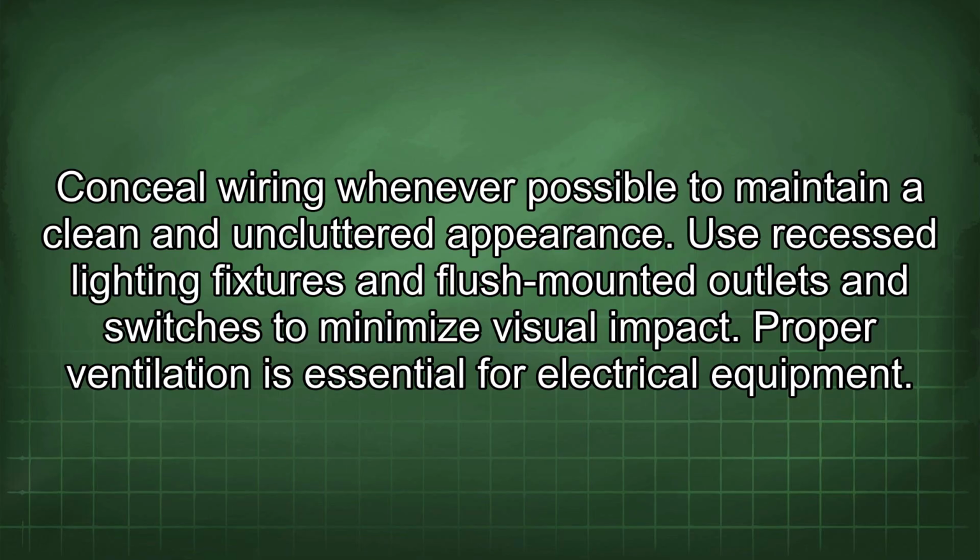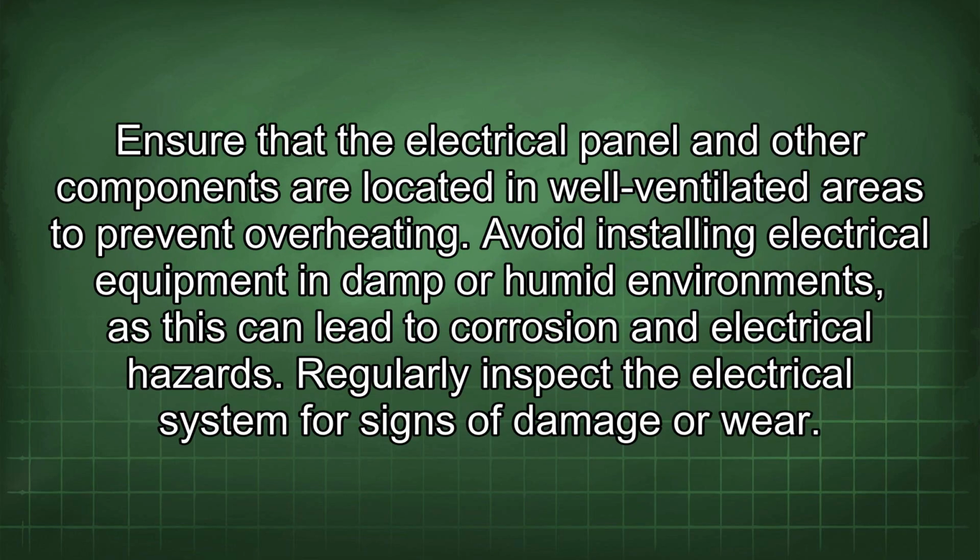Proper ventilation is essential for electrical equipment. Ensure that the electrical panel and other components are located in well-ventilated areas to prevent overheating. Avoid installing electrical equipment in damp or humid environments, as this can lead to corrosion and electrical hazards.